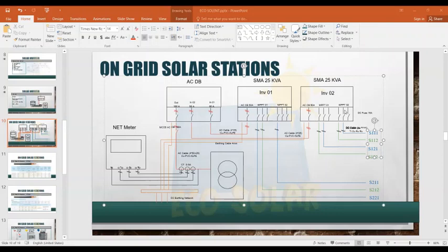It's designed that way for safety, so as not to cause any hazards to the grid, because with no reference it may produce a different frequency that will harm the network. So this one should be synchronized. We use the frequency of the grid as a reference to generate the electricity from the DC.